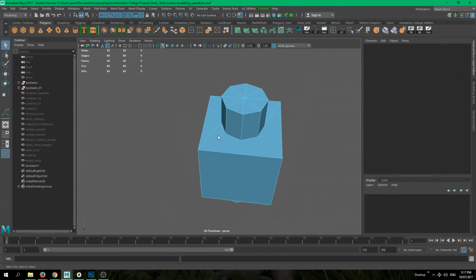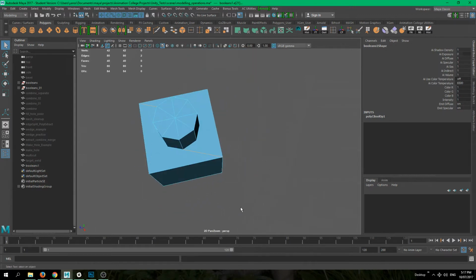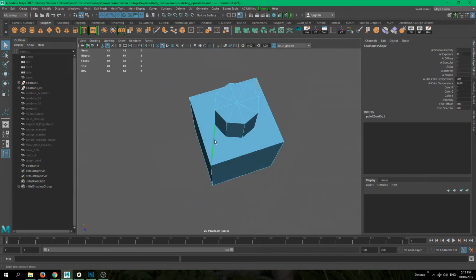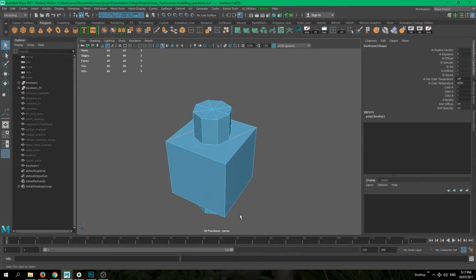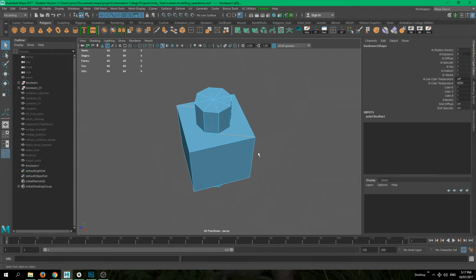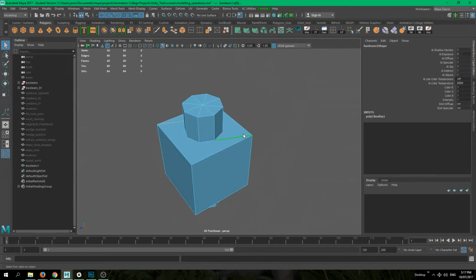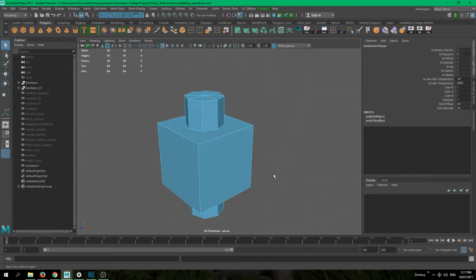It's not going to be too big of a deal, and I'll show you right now how to do it. So first of all, I want to try and get rid of those edges over here really quickly and just see if it actually is going to work or it will break the mesh, because I'm not entirely sure. So selecting all of those edges and Shift right click, delete edge. So it seems to be fine.